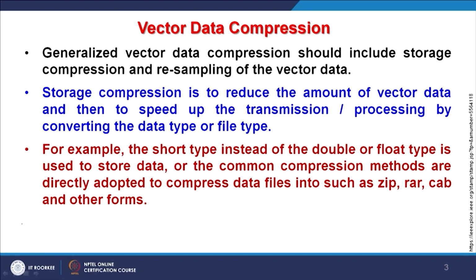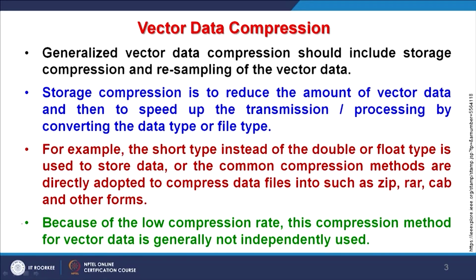So, it is always advisable in real practical GIS projects that we first decide how much area I am going to cover in a particular study or project. Once that is decided, an area of interest, a polygon boundary, maybe a natural boundary, maybe a political boundary, should be used, and data using that boundary should be extracted and kept separately, so that I will not be using the big data file, but a subset of the original data set.